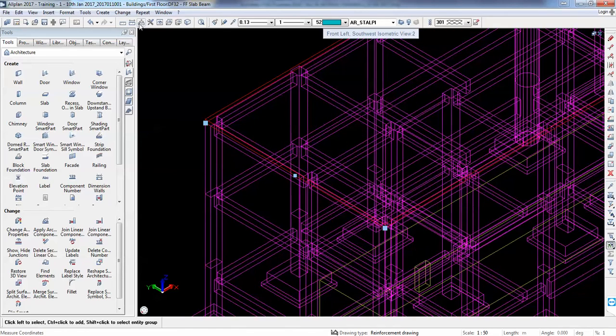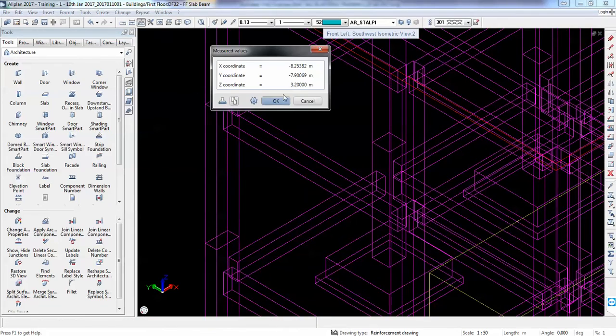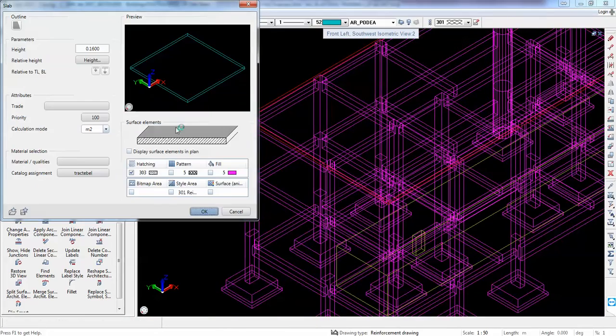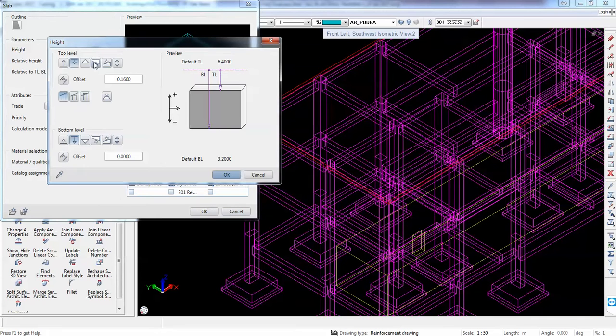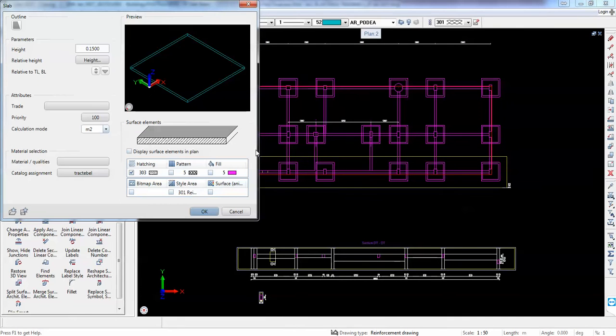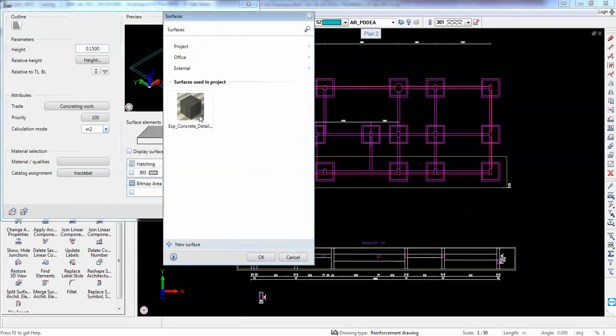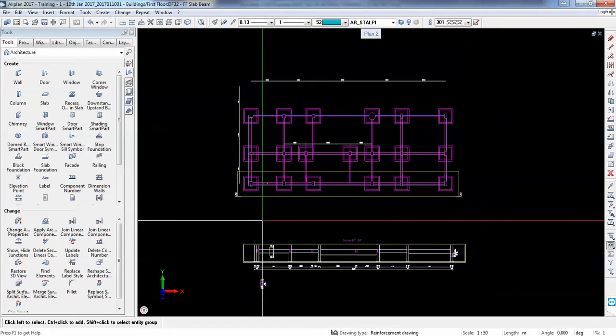I wanted to place it where I'm detailing. So I'll use this 3.2 coordinate. I'll say here 3.2, the low part, and a thickness of 15, whatever. Okay, so now I added the slab. The slab also needs to have this tile area in order to interact with the concrete of the beam. And also I will add this exposed concrete so it will be transparent.